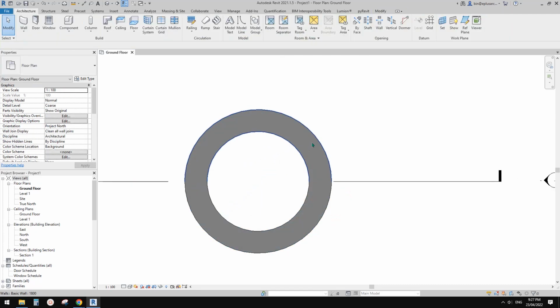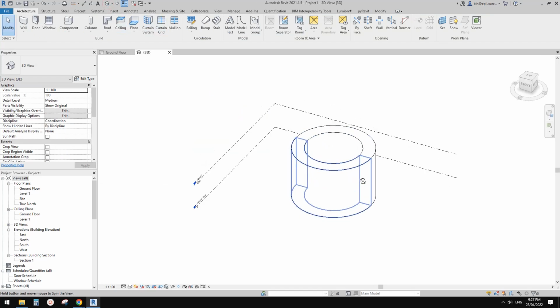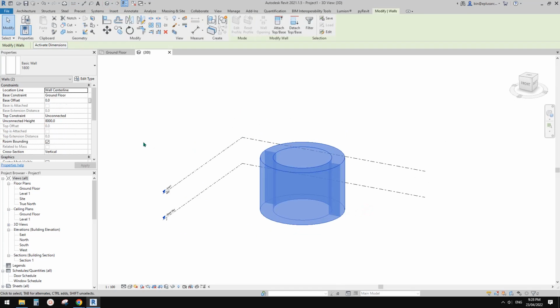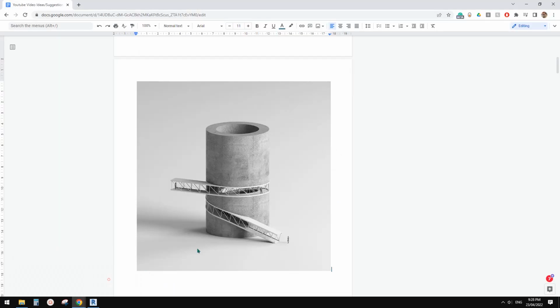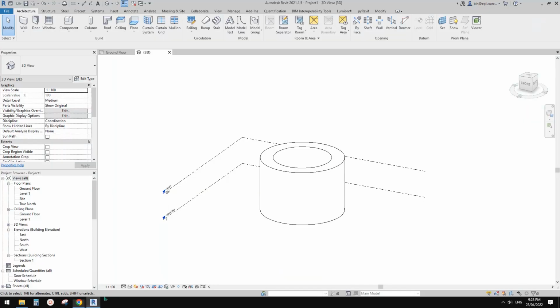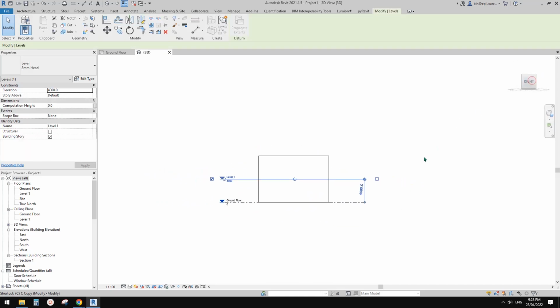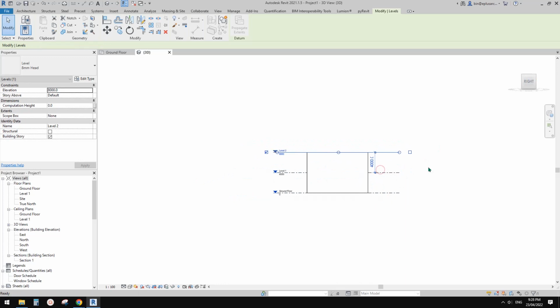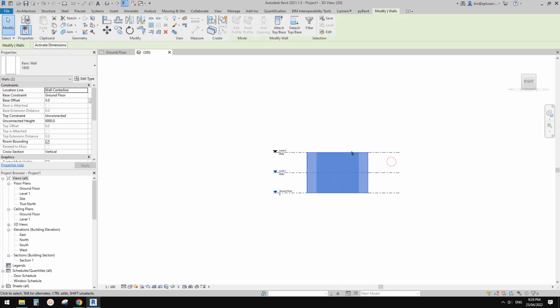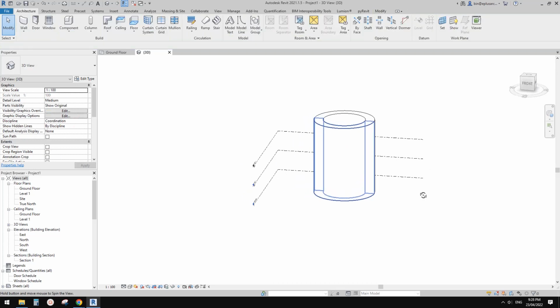That's why I say we're going to create two walls, and of course let's make them a little bit higher. We're going to use this as ground floor, and roughly this will be level 1, level 2. So let's go back. Ground floor, level 1. Let's add another level, CC, add another one. And this wall needs to go a little bit higher, so let's make it 15 meters high. Okay, that should be enough.